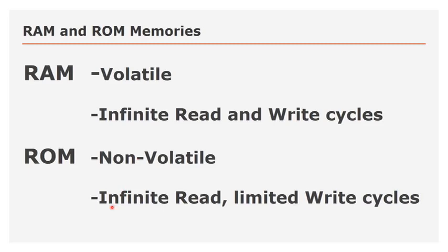The limitation on this thing is you've got limited write cycles. Depending on the device, it could be maybe 10,000 write cycles, which sounds quite a lot, but if you keep on writing to a device, you can actually destroy it within a few seconds to a specific position. But once you've programmed this, you can do infinite reads from it. So that is unlimited, the amount of reads that you can get. But I will explain a little bit more on ROM and RAM memories in the next slides to follow.